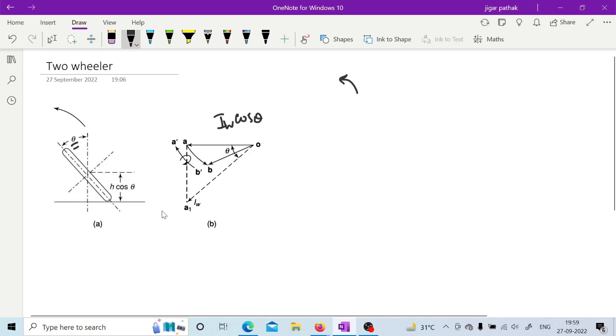In our daily life, it is not that observable, because we are reducing the speed. But if you have observed bike races, the biker is not allowed to reduce the speed while taking a turn. So whenever these bikers are not allowed to reduce the speed, what they do is give this tilt angle in order to achieve equilibrium, because otherwise the couples which are generated may overturn or skid the vehicle.